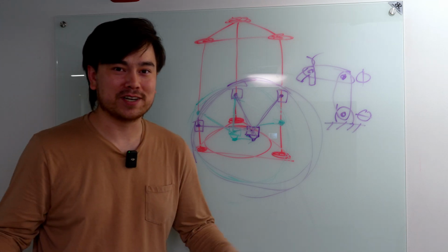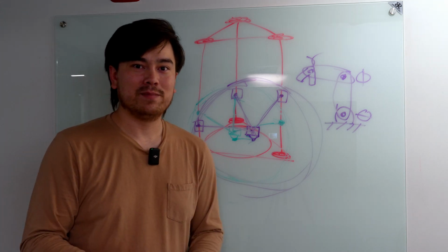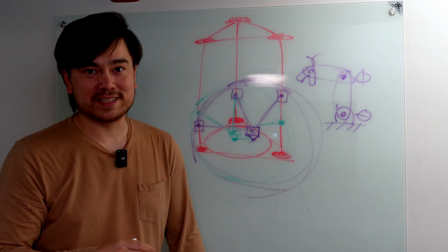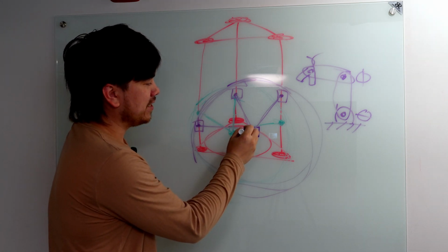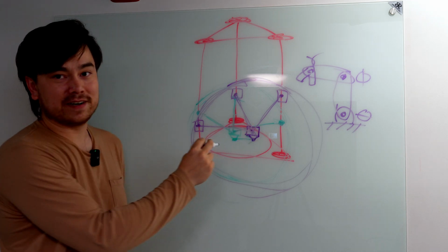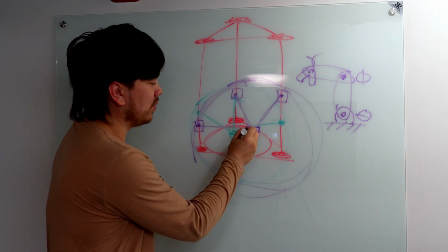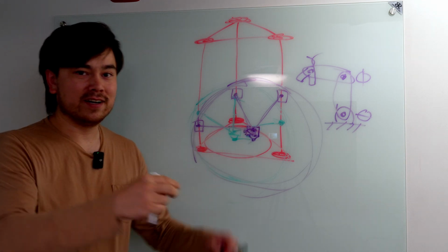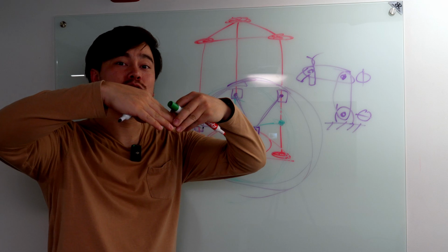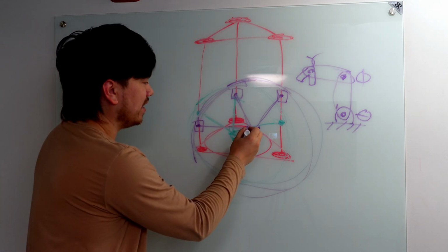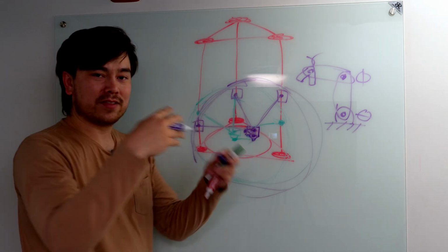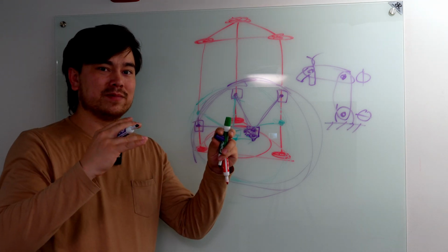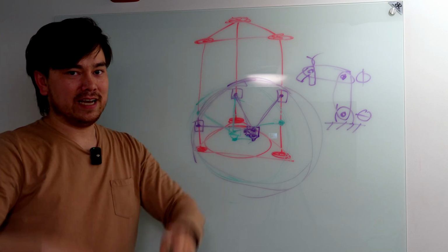Okay, so what do you think? Was that kind of cool to learn about it? Do you understand a little more about parallel kinematic mechanisms and these delta printers? Some interesting things to think about is, in this case, we don't have a single sphere. We would actually have multiple spheres based on where the attachment points on the hot end are. So, you know, they don't all conjoin into a single spherical joint. They're actually at three separate positions. So it's actually three separate sphere intersection problems that are intersecting their own arm.